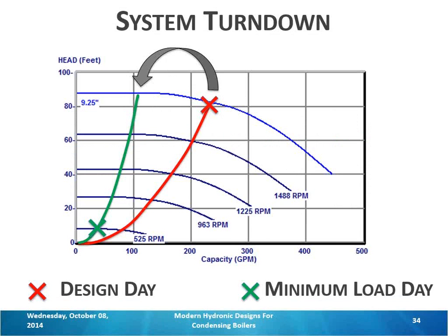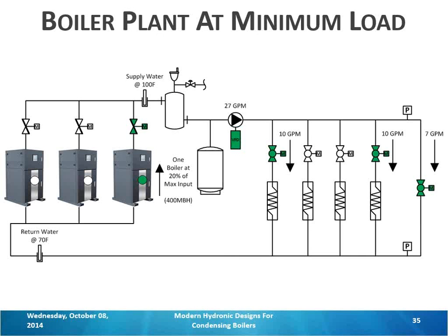What's your temperature range for condensing? I know it's not like maximum. So these are just kind of chosen as an example, but if you want to condense in that boiler, typically it's around 135 to 140 degrees Fahrenheit for natural gas as a return temperature. When you get above that temperature, you're not really condensing anymore. And then the further you go down from that 135, the more condensate you create and the higher your efficiency.